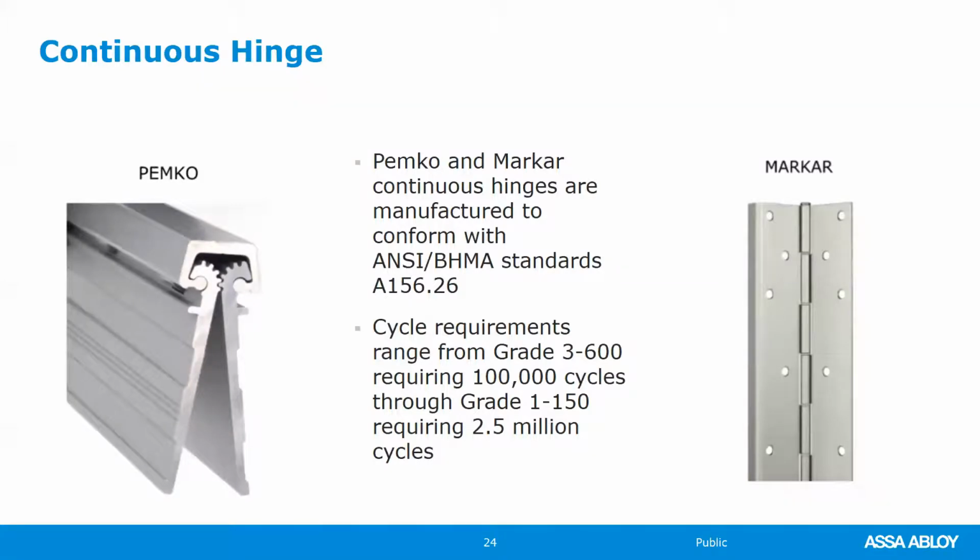They're the full height of the door. Assa Abloy has Pemko and Markar continuous hinges. Pemko are the geared type, most commonly aluminum, and Markar is the pin and barrel type. They have steel and stainless steel available.